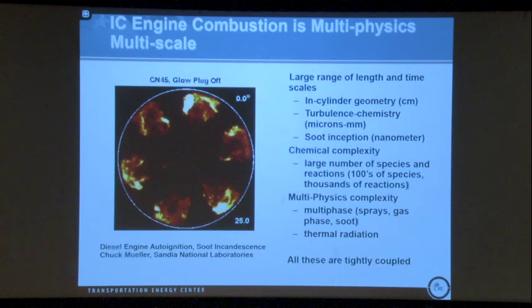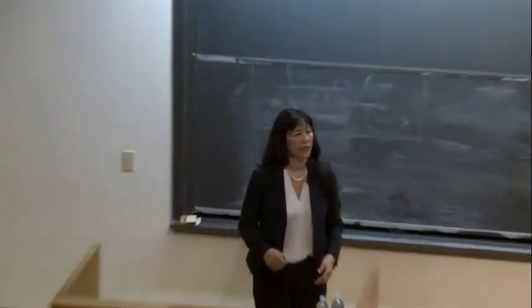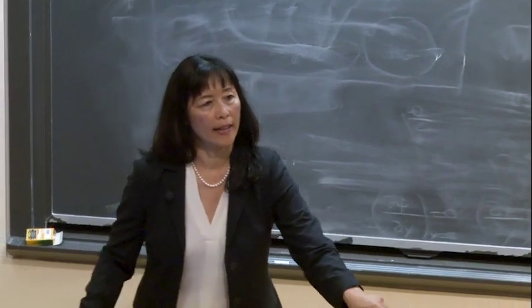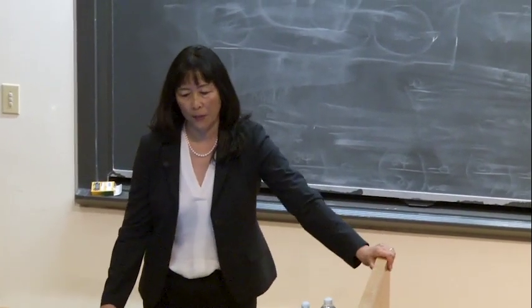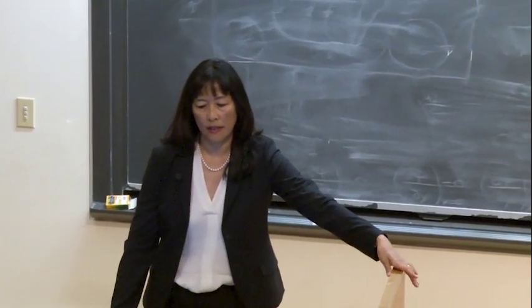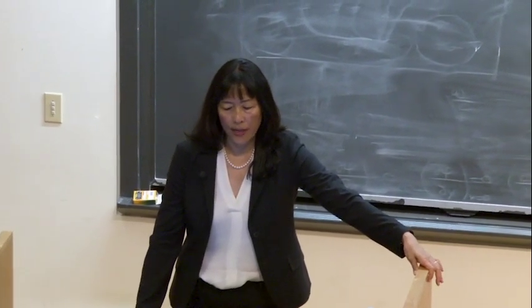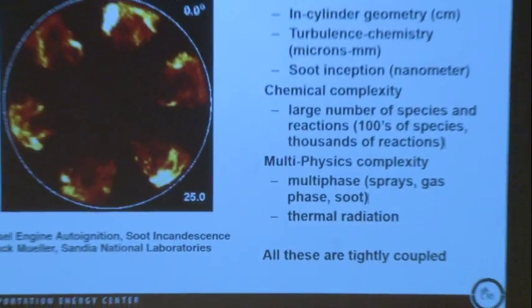It only gets larger when you move to gas turbines or to burners. And then chemistry, when we talk about flame scales, we're talking about millimeters or submillimeters, and when you get to fine resolution of the internal structure of flames or of ignition fronts, you're talking about microns. And as we move up in pressure, flames get thinner and ignition fronts get thinner, and so the spatial resolution gets even smaller.